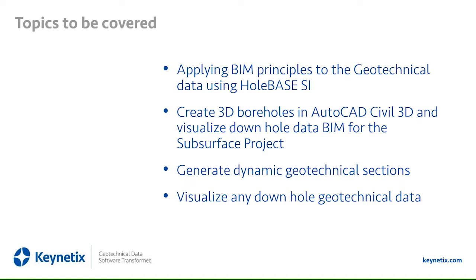So what we're going to do in this webinar is cover some of the steps to managing your data, controlling it inside some software called HoleBASE Si, then look in more detail at how we can go and start visualizing it, bringing those 3D boreholes into AutoCAD Civil, creating surfaces, doing those dynamic sections, and looking at how we can visualize other downhole data, perhaps like water strike locations, perhaps levels of contaminants across the site, and we'll look at that in detail as well.